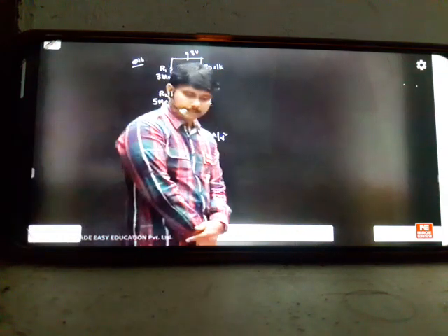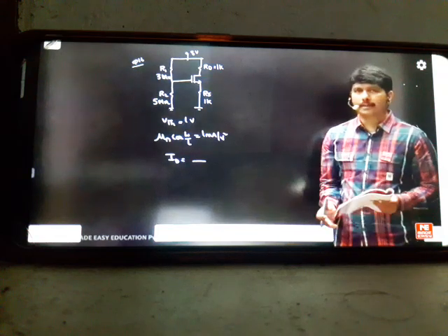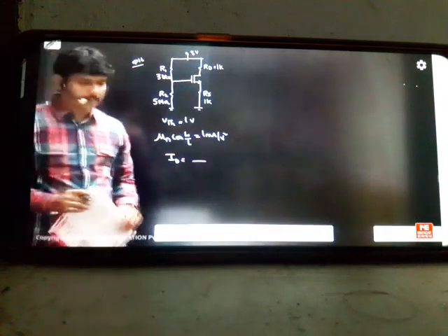Yes sir, that's correct. If drain and gate are shorted, you can say it is in current saturation. If gate and source are shorted, you cannot believe it. It can be anything. It can be triode or it can be in current saturation. Just try to solve this problem.